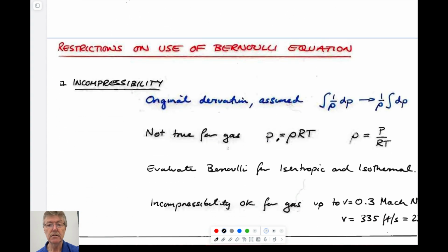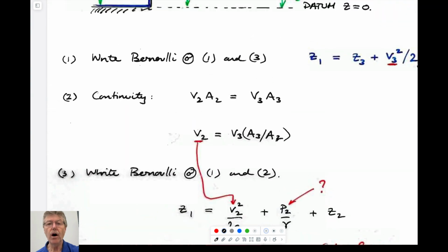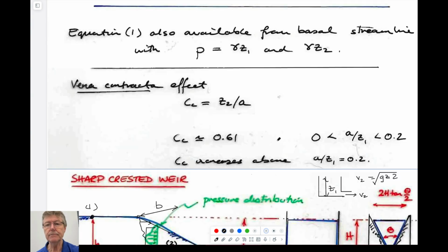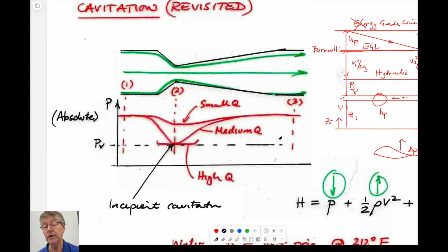I guess the last things, yeah. So we'll actually go back to what we talked about before. We talked about grade lines and what Bernoulli means if we draw it in this way. So this is quite a useful way to think about Bernoulli, that this grade line here is really the fact that Bernoulli is constant.